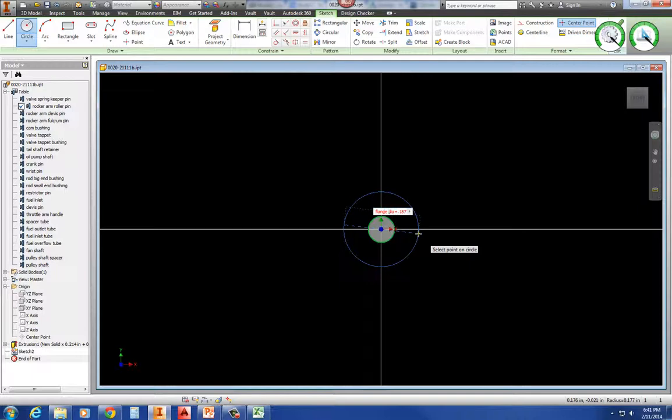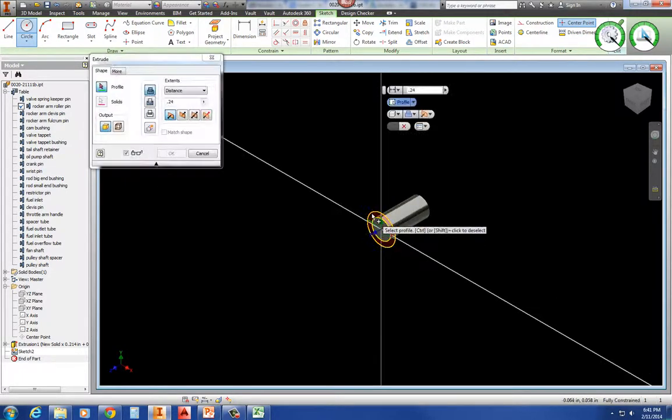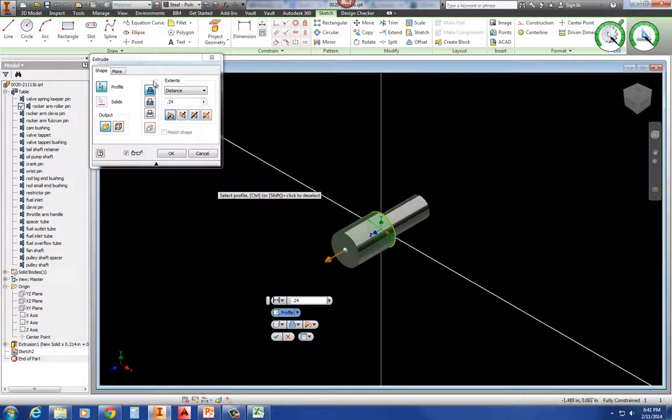Now watch this. I can type it right into the dimension. So let's see if we can put an underscore. Yeah, it just doesn't like spaces. Flange diameter, 187. So if any of those changes, which they don't, not in these, but we may have one that changes later on, right? So let's go ahead and put that in. I'm going to extrude both of these shapes, and that thickness is 0.025 on all of them.